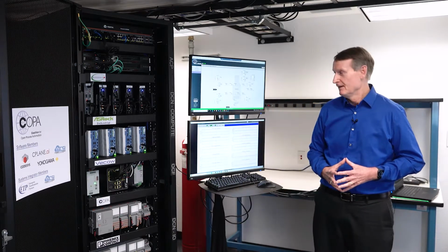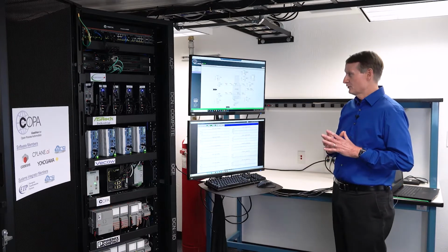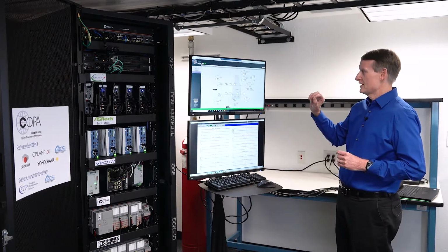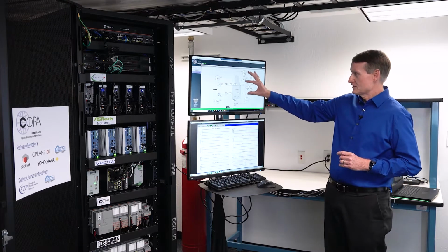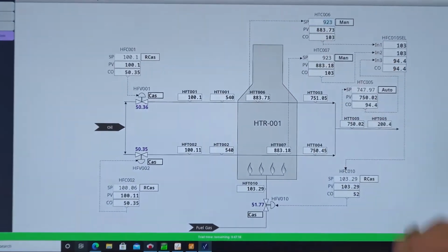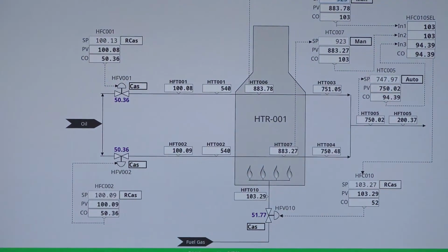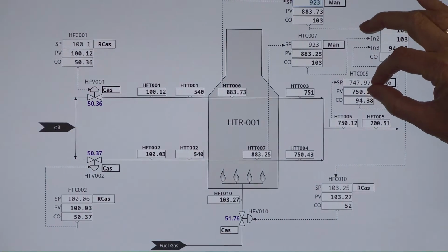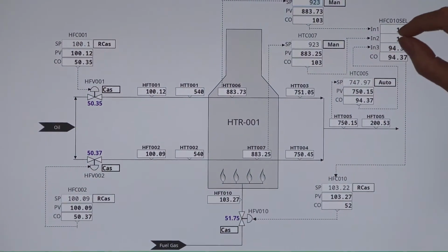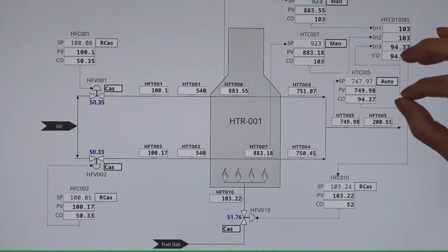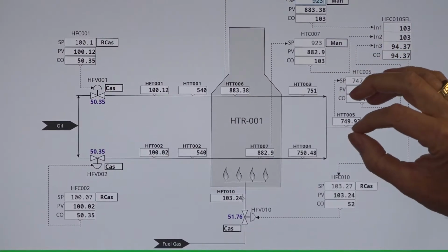Okay. Now, as part of that, we can program some priorities into the control. And so what we've told it is that the top priority is those tube skin temperatures that we talked about earlier. We don't want to violate those limits. And we've told it that we would like to maintain a set point on the outlet temperature. And we said that is more important than the total flow rate constraint. So if we have room, we want the total flow rate as well.